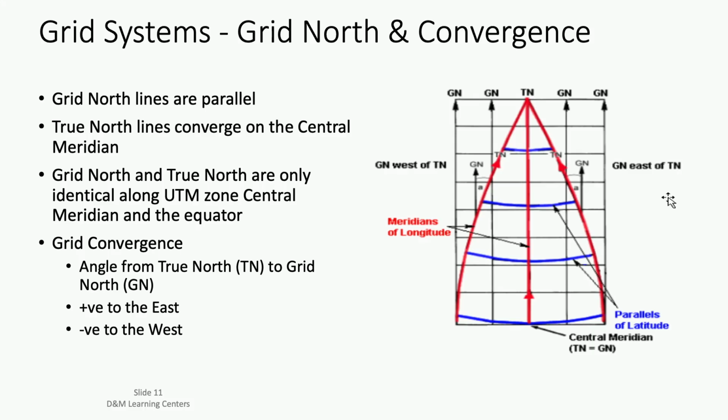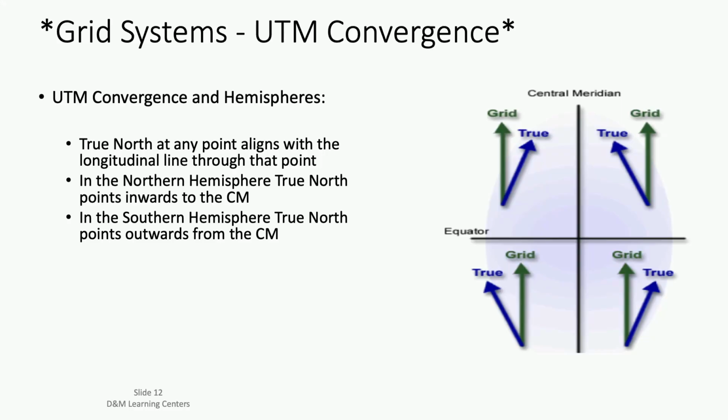So this is kind of an overview of our grid. We utilize grid north and true north. Most of the time we just use true north, and same with magnetic north. We have to offset our drilling, so we have to be quite precise on where we're going to hit our targets. Some of our targets are anywhere from 5 feet to 100 feet in diameter, so we need to make sure that we're spot on where we're going to hit, so we have very little room for error. So we utilize all of these to make sure that our calculations are exact. And kind of the same thing: depending on where we're at on Earth, we have the plus or minus for our grid and true north.